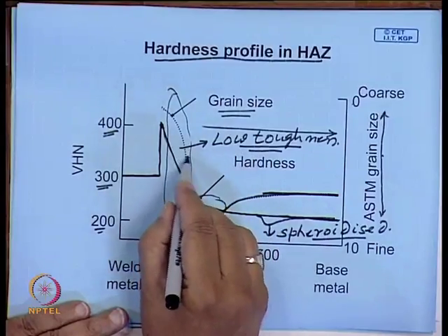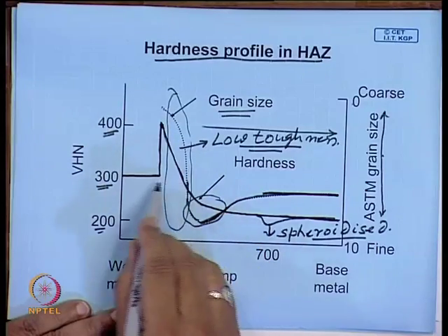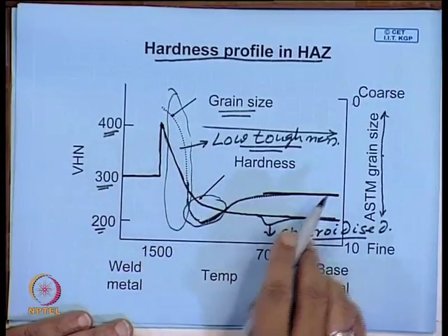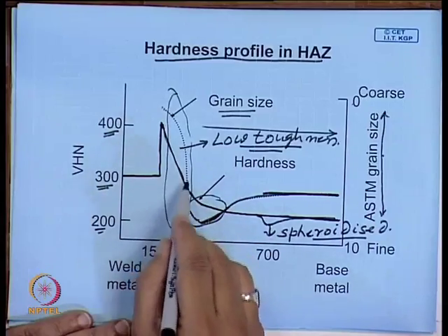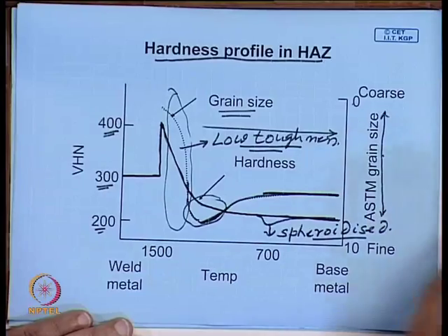If the welding electrodes are wet, not properly dried, if the slag layer on the weld pool is not protective enough, or the surrounding gas environment which is maintained is not protective enough, this hydrogen can diffuse into these regions, and we may not see the crack immediately, but after you have welded and leave it for some time, you find there is a delayed cracking. Hydrogen relates to delayed cracking, which is a major problem.